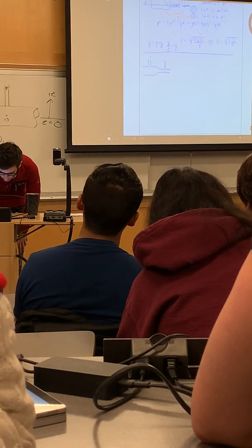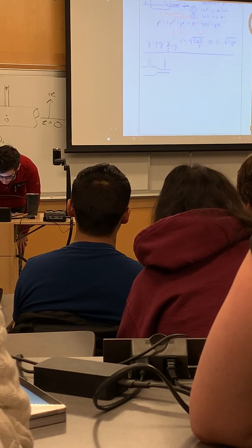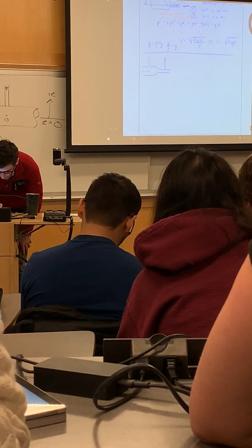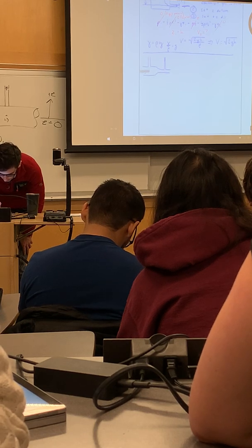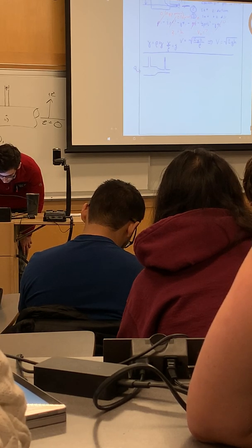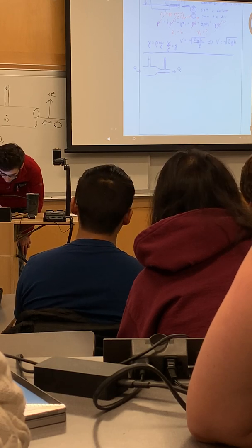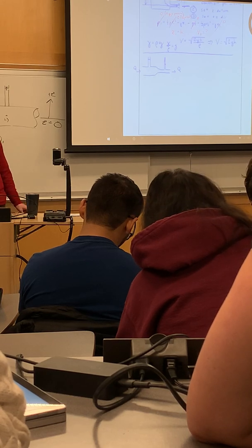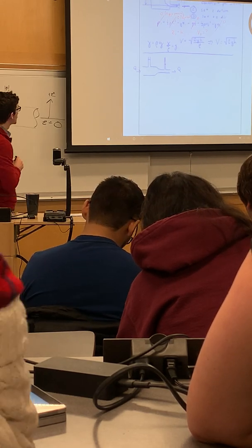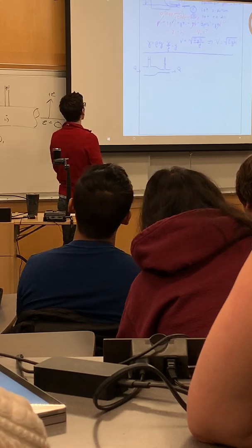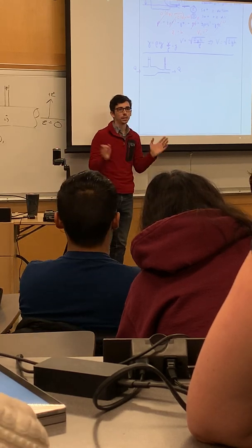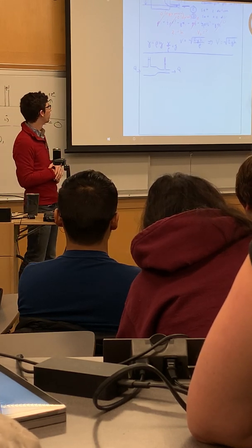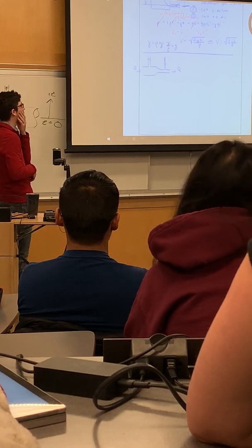So you might be given an example where you have what's called a Venturi constriction. And you might be told something about the nature of the flow moving through this. And then you might also be given piezometer elevations. Right? And you might be asked to solve for Q or solve for delta H, given certain information about the problem. Does this premise make sense to everyone?